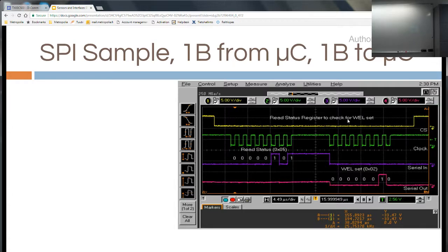And the same thing, I think this is writing and reading. So chip select goes down. The first byte, that data is the MOSI signal. So the master sets byte 05 for the system. Yes. And after that, the next byte sends 0, but this is what comes down.